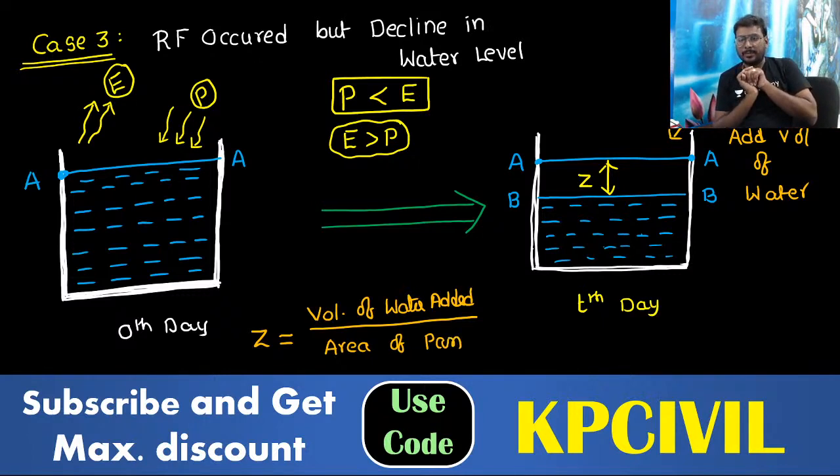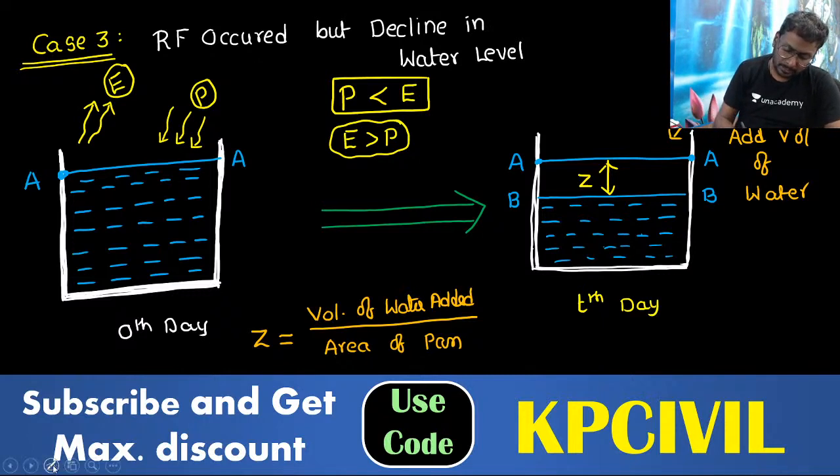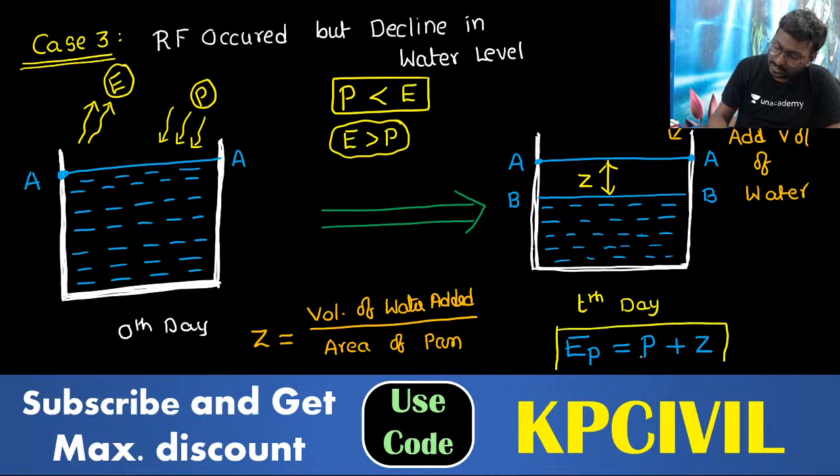Same case. Add a certain volume of water into the pan, measure how much you have added, then divide by the area to give Z. Then what is EP, the pan evaporation now? Shall we take EP equal to Z? No. Both the precipitation and Z will be considered. EP is equal to P plus Z. Don't take EP equal to Z.